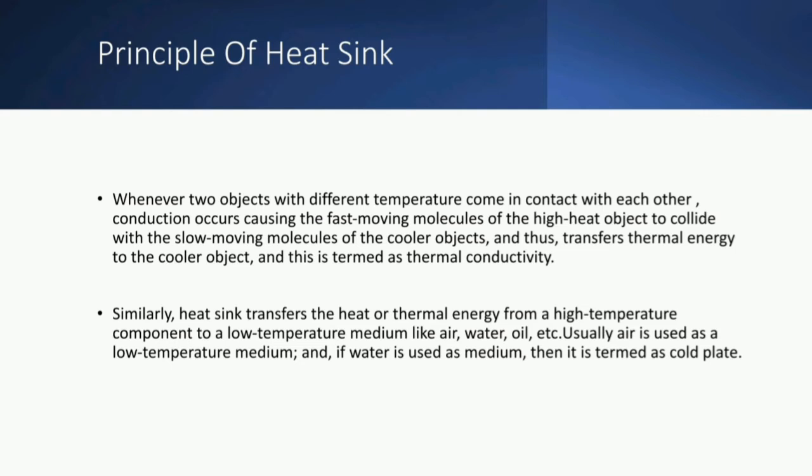Similarly, a heat sink transfers the thermal energy from a high temperature component to a low temperature medium like air, water, oil, etc. Usually air is used as a low temperature medium, and if water is used as a medium, then it is termed as a cold plate.